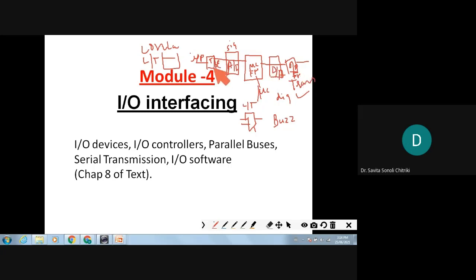I was telling, you can visualize your microphones. Your microphone is there at the input side, which is generating the analog signal that is converted into digital and it is being given to the processor there. So your voice will be modulated, right? And if any noise is there, all that will be removed, and that is finally sent to the speaker here, right? So the speaker also wants the analog signal. So again, you need at the output side a digital to analog converter.